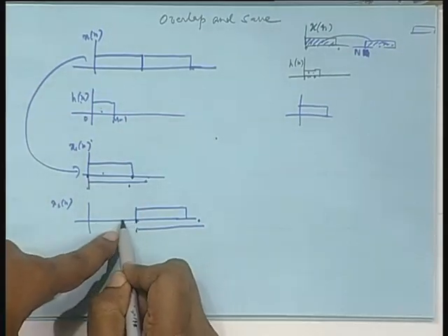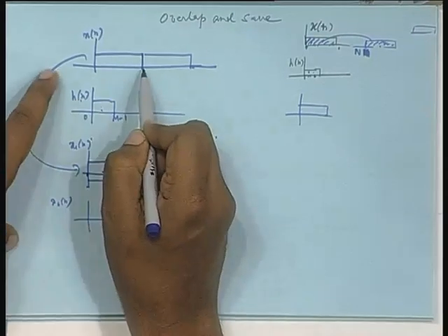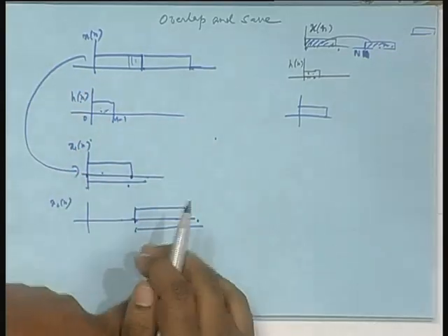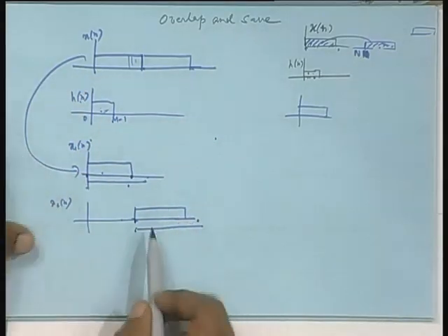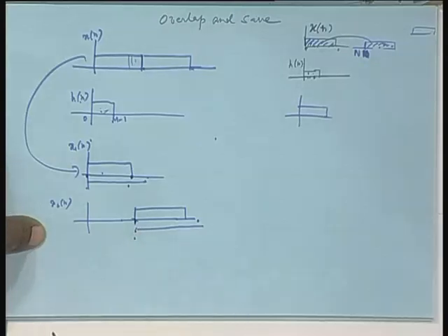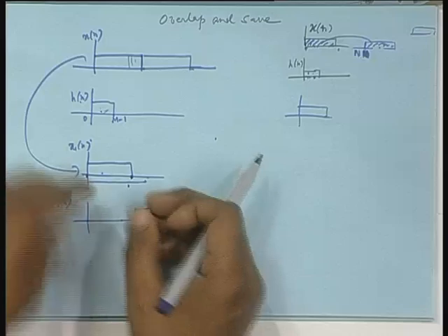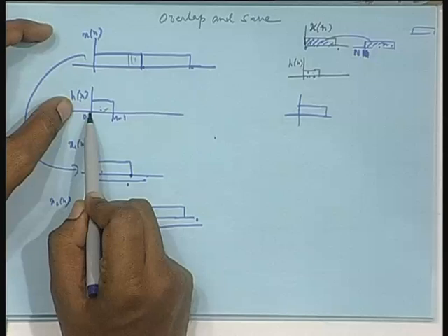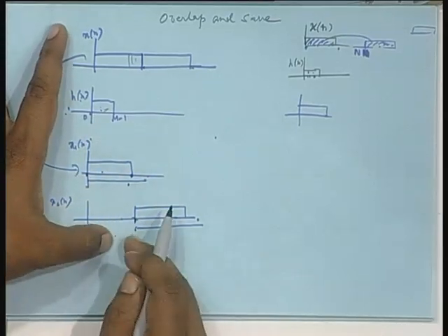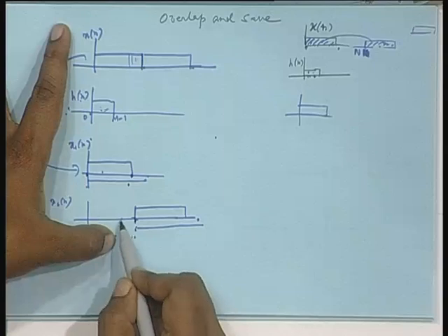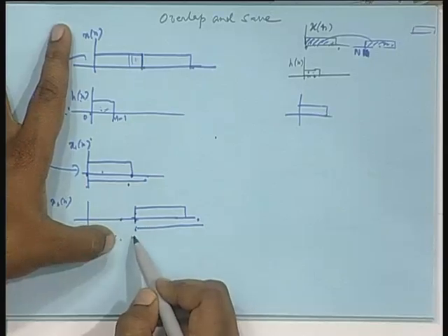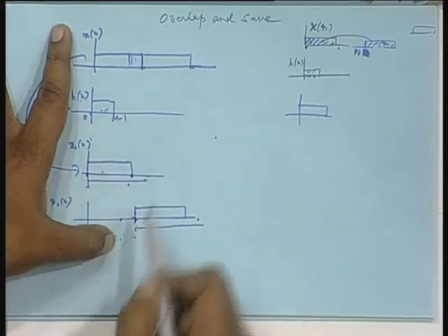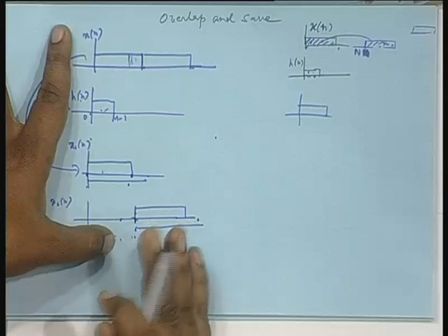But to the left of this, there is no data, whereas in effect when I was doing convolution, there was data coming from this side, that was getting multiplied by part of this, that will be missing, is not it? That means, here if I do this convolution at this point will be wrong. Still again, if I reverse it, 0 to minus of m minus 1, that entire thing comes here. They multiply by 0 here and only one sample. So, you get some result, but that is wrong, because in effect there was no 0, there was data, but you have made it 0 here. Fine, you understood there is something that is wrong.